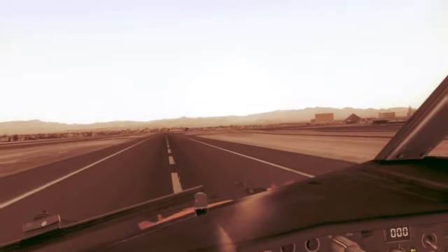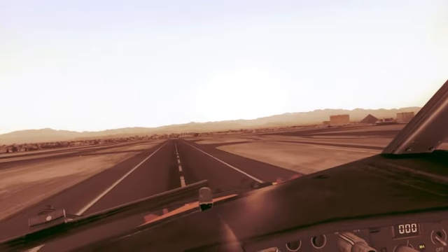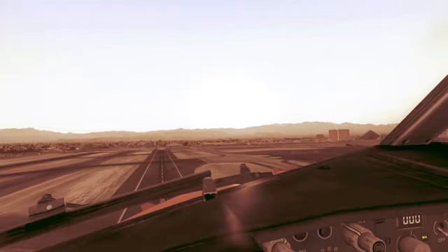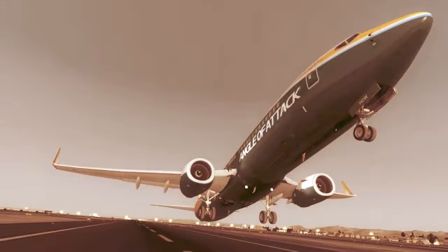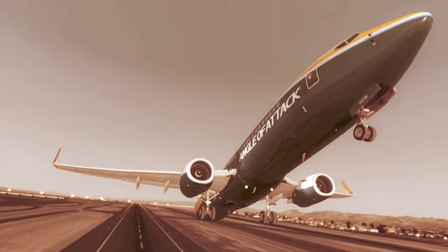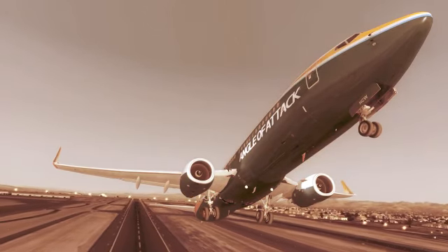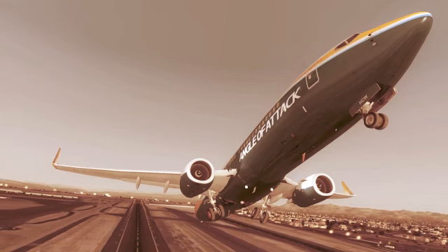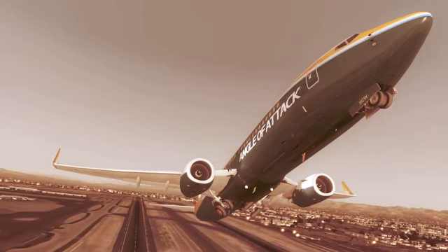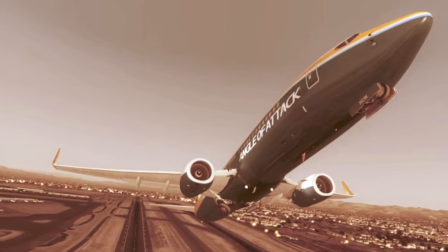If you picture a hot day at a short but high runway, and the engines are not producing their maximum thrust, the takeoff distance may be increased by a huge factor. Huge enough that there will be an enormous chance of a runway excursion if the takeoff is attempted. Under these cases, flight crew on a 737NG may perform a bleeds-off takeoff.